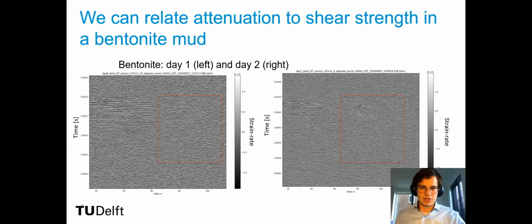The second part is to show you some very interesting observations of the near field strain signal. We are able to reproduce it with the analytical solution of a simple model structure, the homogeneous isotropic media. And we expect to see more applications of this signal in the future for monitoring of hydraulic fracturing operations.